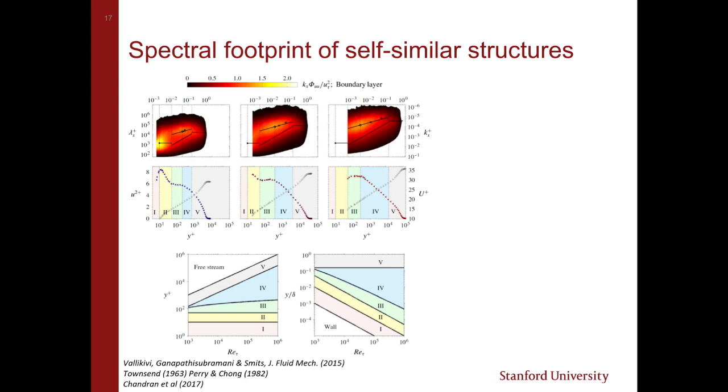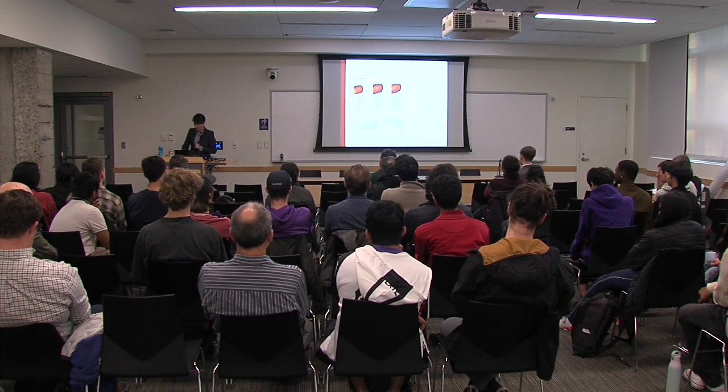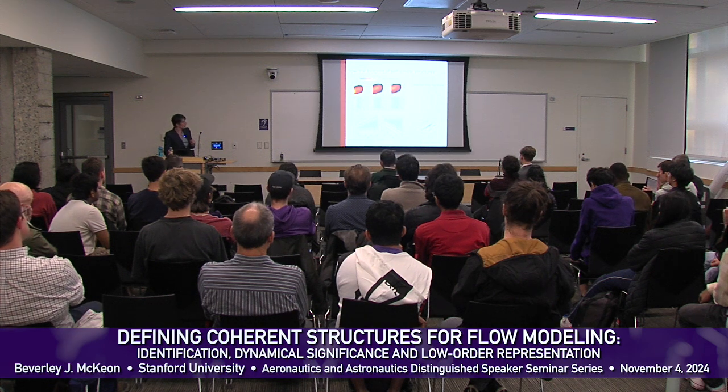They said actually there's two. There's one where the mean is logarithmic, but, or at least they say there's a very tiny region where both are logarithmic here. So there's green, just the mean, blue where both are, and the blue one is the one that grows faster as I go up in Reynolds number. And so this is what the various proportions of the boundary layer height look like as you go up in Reynolds number. So the question is, can we understand this by thinking about the structures in the flow?